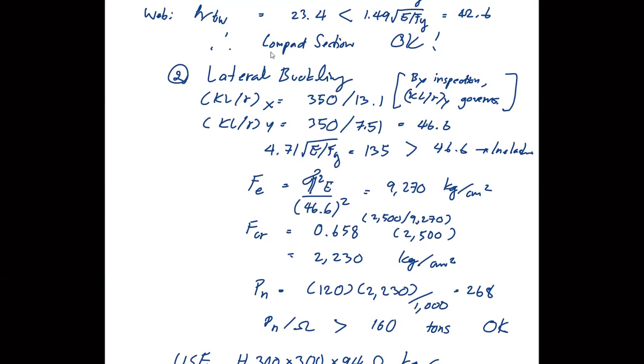But I am okay if you don't feel this. You carry out the calculation a few times and then you feel it, and then you become more confident that actually the greater number in the slenderness ratio would mean that you're going to get the smaller load carrying capacity in that direction. That becomes your answer anyway.